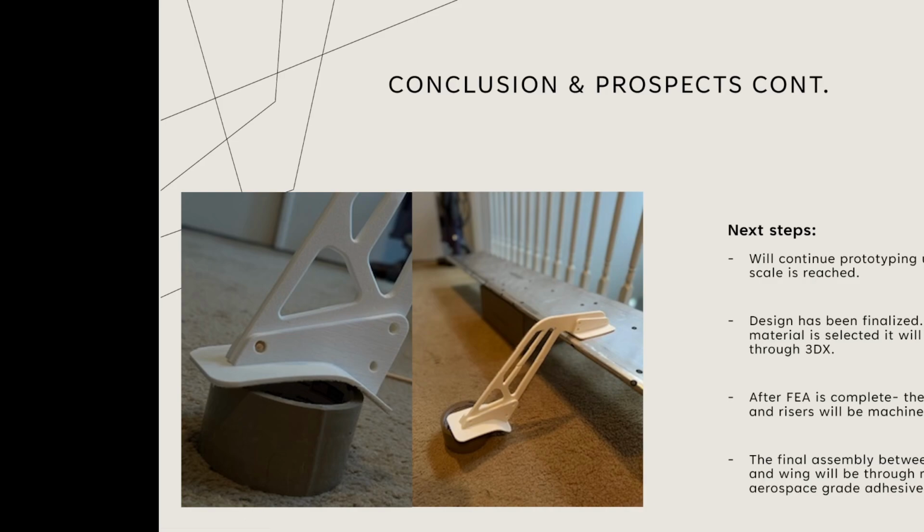And yeah, planning on attaching this bracket to the wing, either through rivets or through just aerospace adhesive. Gonna have to do more research there. And then the bracket that gets attached to the car side will be bolted through. It sits pretty much right on top of the latch for the hatchback. So I'm hoping that since the forces will be transferred right through there, it'll be able to go to the frame more effectively, and we won't have any issues there. But time will tell once again.